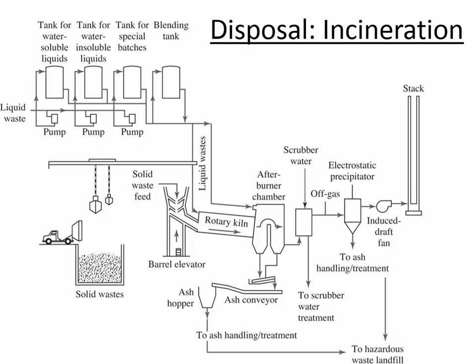Another thing I want to point out is look at what they're doing with the gases. The fumes or the output gases from this burning chamber, they have to put through a wet scrubber. Inside the wet scrubber there's like a spray, and so any particles that would be coming from the exhaust fumes, or if it's a caustic gas like an acidic gas, those materials are absorbed by the water, and then the water has to go to a separate water treatment assembly.